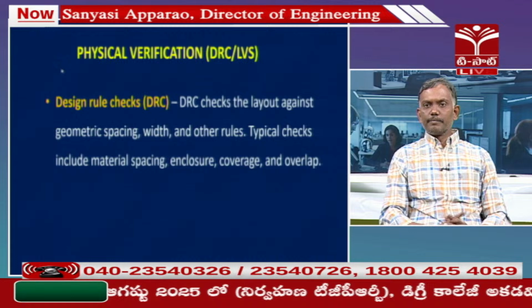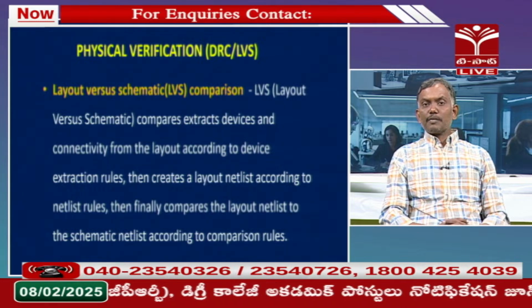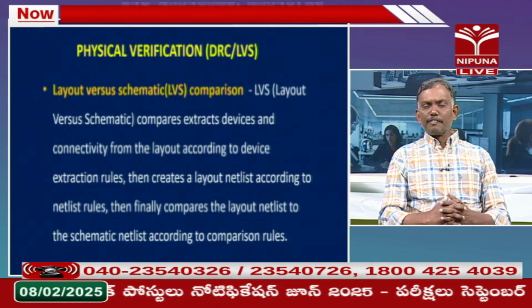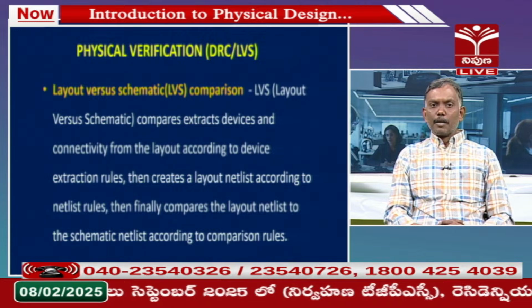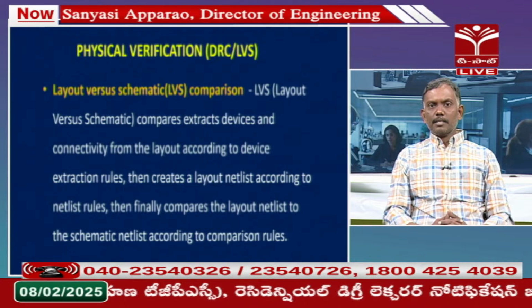And also LVS, layout versus schematic. What is the layout? Your GDS2 is our layout, which contains all the design information from the device level. GDS2 is a device level format, you have only layers. So, for the complete chip at device level, we need to verify DRC as well as LVS. Our GDS2 is the layout, and we are dumping one more netlist with the PG pins as a part of our outputs.